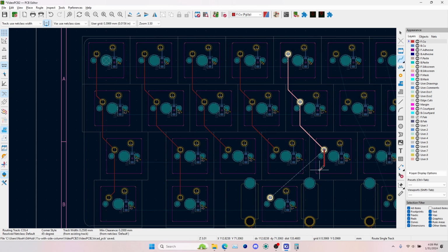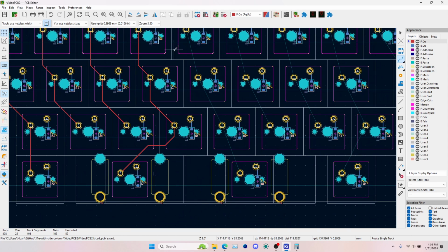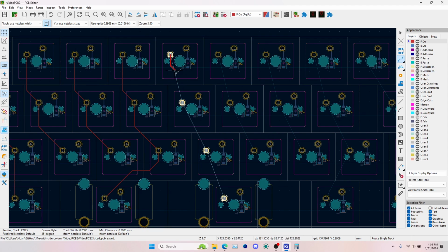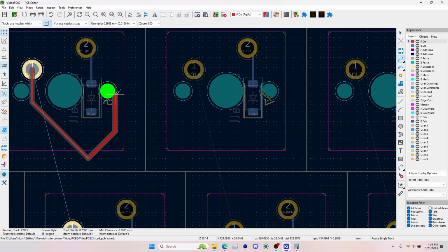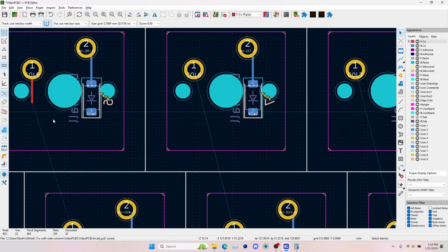And then this one we'll just take out a little horizontally like this. There we go. Now I'm switching the direction of the bend using the slash key. So right now it's going over and up, but if I wanted to go up and over, I could move the mouse around. It's kind of tedious. Or I can just hit slash, which is your slash question mark key, and that changes the direction of the bend. I find that pretty useful, especially when routing closer to the MCU.